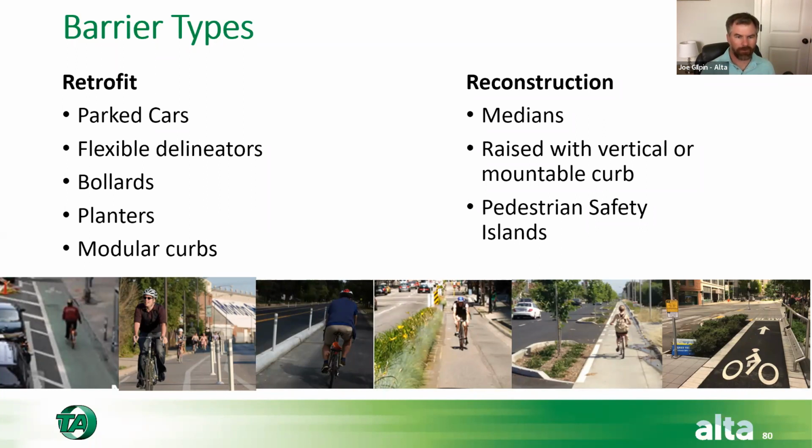So Matthew's asking, how do we approach the clear recovery zone next to the travel lane? So that's an interesting concept. The clear recovery zone is a very, shall I say, strong level of opinion for a lot of different types of engineers that think about that. Now, what FHWA actually says is that if you have an urban roadway, even on an NHS route under 40 miles an hour, they do not require any type of clear zone. So they actually removed this from their 13 controlling criteria back in 2016 for your design criteria on highways, essentially. So if it works for a highway, it's going to work for a city.